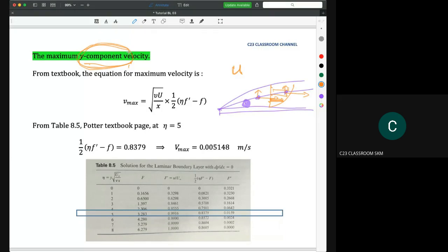Okay, so according to the textbook, I think I simplified it here. You could read from the textbook; at the end of this question, I will give you notes about this. It actually depends on the streamline. We know that if we have one streamline like this, which is psi, we have u here and we have v. So u here is actually d psi over dy, and then v here is actually equal to negative d psi over dx.